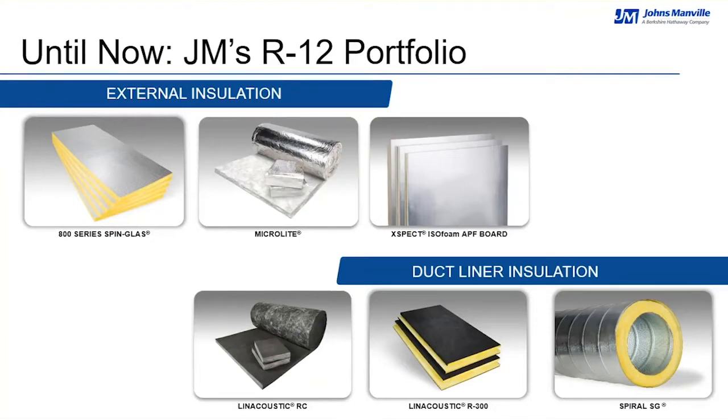For internal duct insulation, Johns Manville's Linacoustic RC duct liner and Linacoustic R300 board are available in a 3-inch thickness. JM's Spiral SG for double wall applications is available in type 125 or type 150. These products achieve an R12 or better performance for lined ducts.